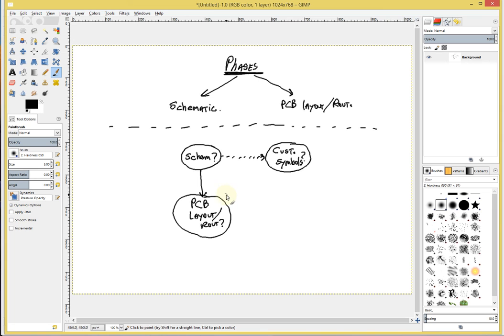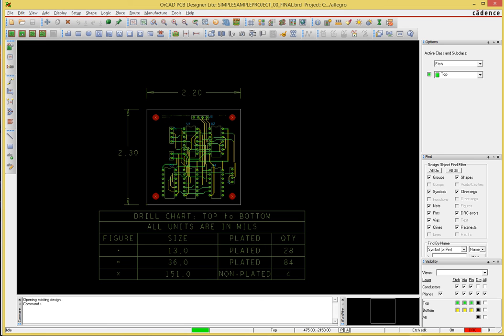Okay, layout means that you just place the components and lay them out spatially in two-dimensional space on the board where you think the parts are going to be. The routing consists of basically laying out the traces, or drawing the traces, in accordance with the net list that you generated from your schematic. So we're going to explore this in a separate video.